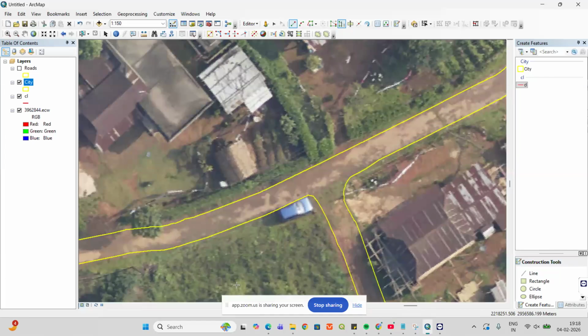The DGPS point is our responsibility, not the freelancers'. We have MOUs with 10 to 15 more companies, and we'll sublease the work as far as the DGPS point is concerned, but we'll give them the location. Sorry, I meant the ground control point marking. The GCP will be marked with DGPS equipment, and we'll be outsourcing it.